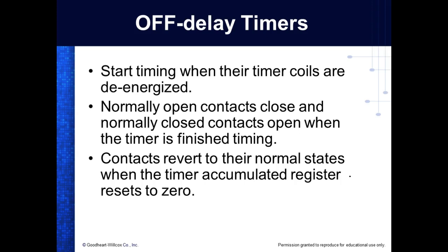Normally open contacts close and normally closed contacts open. So here, the only time that we really get concerned with examine on and examine off is on that stop button. Normally after that, we almost always just use this one right here. Normally closed and normally open, right? You understand that?